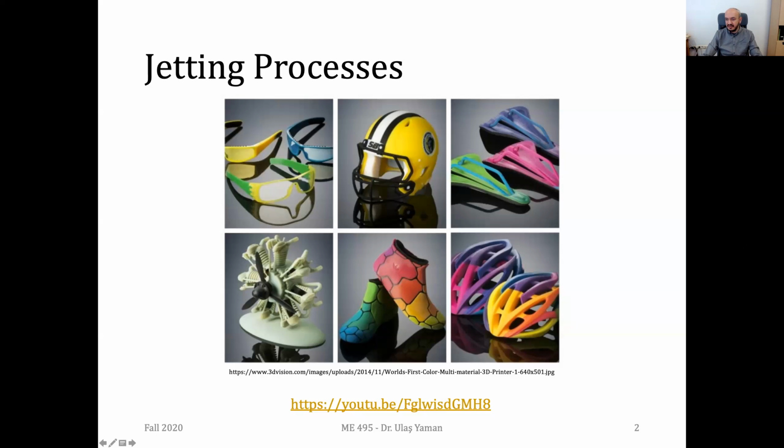And Hussein has a question. So what happens if you have powders inside the parts? We don't have such cases, Hussein. It's not possible in powder bed fusion processes. You can always produce solid parts. We don't have infill percentages in the powder bed fusion CAM software. It's only possible with FFF.